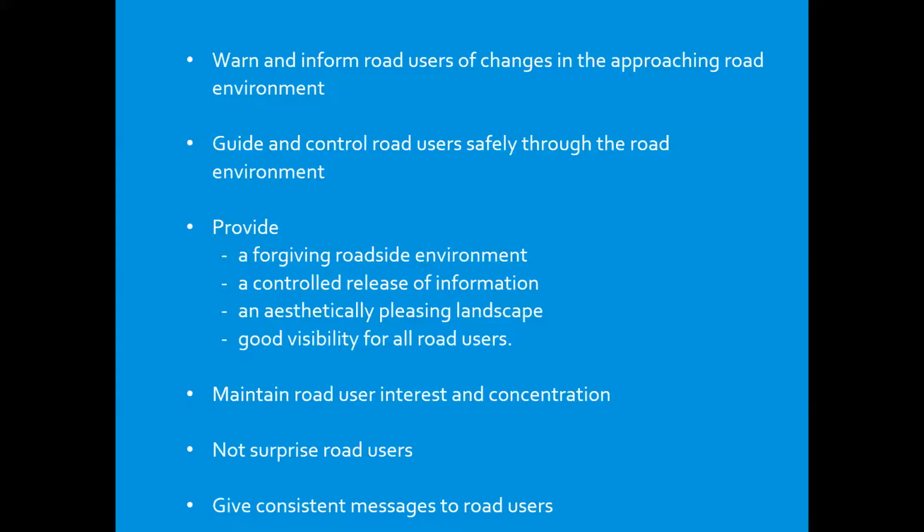Although most design guidelines focus on road design features, the psychological aspects of drivers' behavior are always present. An error in perception or judgment, or a faulty action on the part of the driver, can easily lead to a crash. Roads should be designed in such a manner that only one decision at a time is required from a driver, ensuring that he or she is never surprised by an unexpected situation, and that adequate time is provided to make the decision.